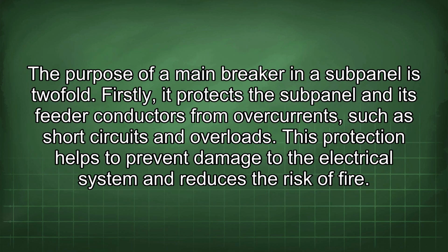The purpose of a main breaker in a subpanel is twofold. Firstly, it protects the subpanel and its feeder conductors from overcurrents, such as short circuits and overload. This protection helps to prevent damage to the electrical system and reduces the risk of fire.